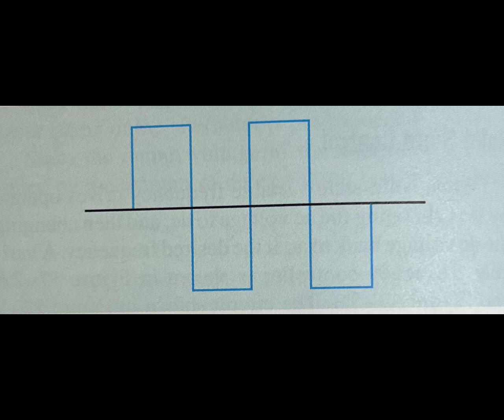A choke coil and capacitor bank are used to filter the output voltage of the rectifier before transistors Q1 through Q6 change the DC voltage. An electronic control unit is connected to the base of the transistors Q1 through Q6. The electronic control unit converts the DC voltage back into three-phase alternating current, turning transistors on and off at the proper time and in proper sequence.